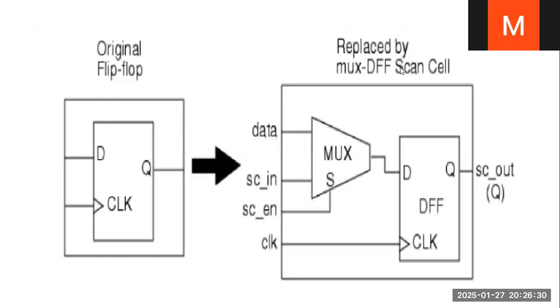Good morning. Today we are going to learn how the scanning session takes place. In the scanning session, we are converting the original flip-flop to the scannable flip-flop by appending a mux to it.